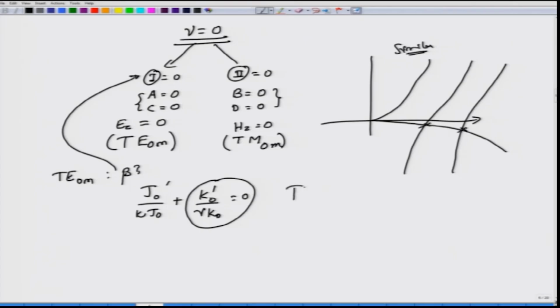So, for the same TE first order 0, you will have multiple modes M, starting with M equals 1, 2, 3 and so on, and correspondingly you will have beta for the TE 0M mode. So, what are the field components for the TE mode? Well, for the transverse electric mode it is Hz, which must of course be some constant B which you do not know, but anyway. So, the fundamental Hz field should be J0 kappa r. And is there any dependence on phi? Well, there is no dependence on phi.